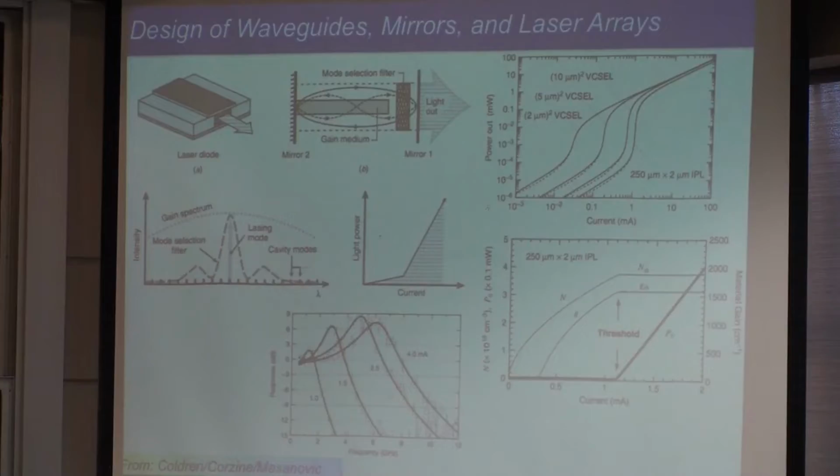Okay, so that as an example is semiconductor laser, and what I want to spend a few minutes talking about are some of the internal design parameters of the laser. So the gain spectrum we have already talked about. You design it by choosing the active region, quantum well size, thickness, material, and all that. That will design your gain spectrum for a semiconductor laser.